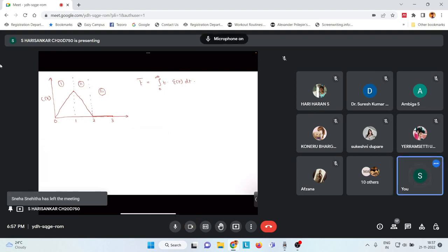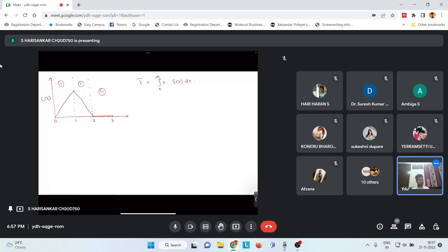Okay, sorry about that. So now the thing is, we have the C versus T curve. What we need to know is that E of T will be C divided by the integral from 0 to infinity of C of T dt. So from this question, the area is one. We need to find the E curve first so that we can apply this formula.